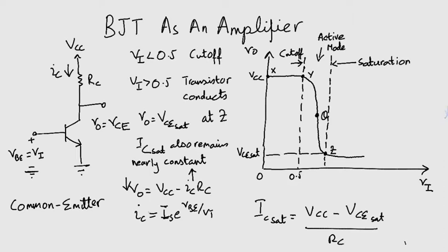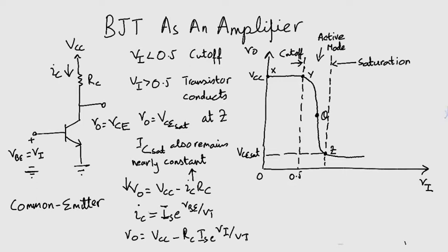Next up we find the voltage gain. For that we need to express V0 in terms of Vi. Here we are at the bottom of your screen. We are going to differentiate that, dV0 over dVi at the point Q. Remember that the voltage gain is specific to that point. To explain the voltage gain graphically, we see the blue line on our graph. The slope of this tangent to the transfer curve at point Q is basically the voltage gain of the amplifier for small input signals around Q.